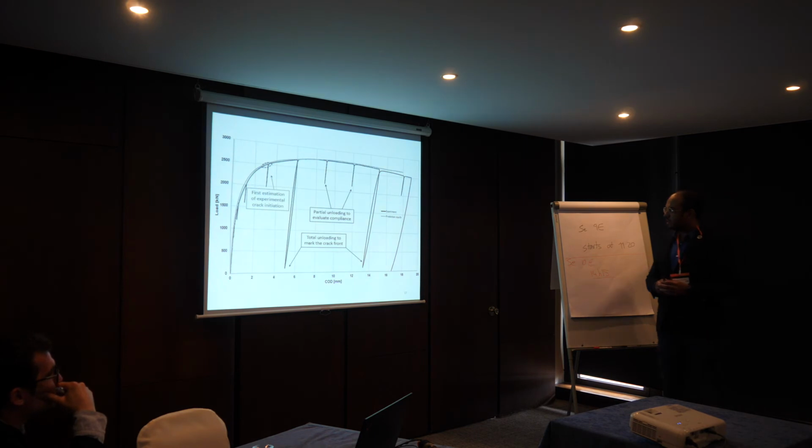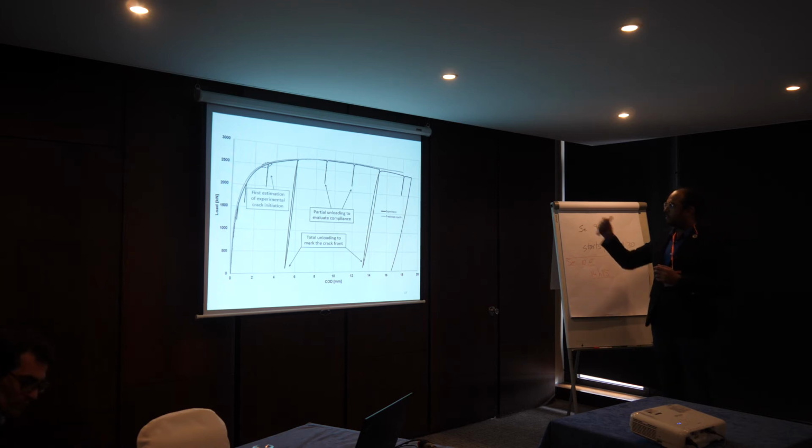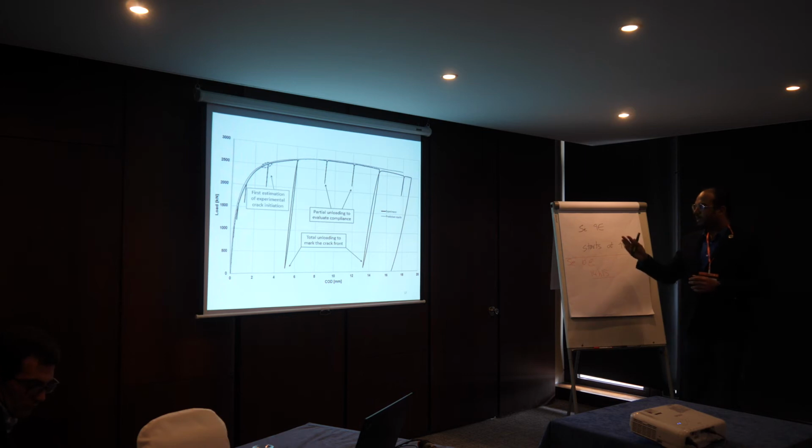As you can see here, this is the difference between the experimental and my simulation. After finding my GTN parameters, I could make one simulation, shown in gray color, and predict the failure of the pipeline based on the GTN model. But it took, as I told you, 1 month, so it's a lot of time.